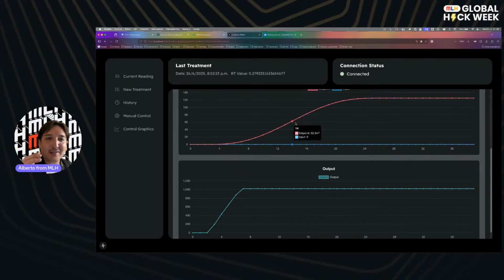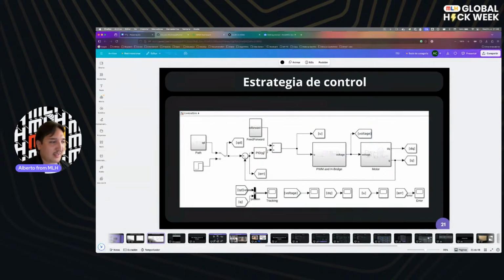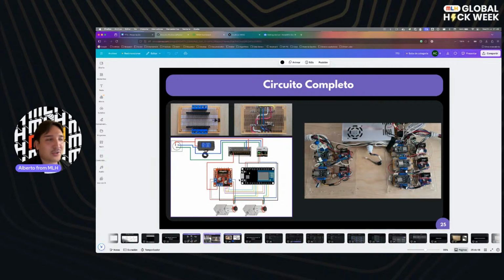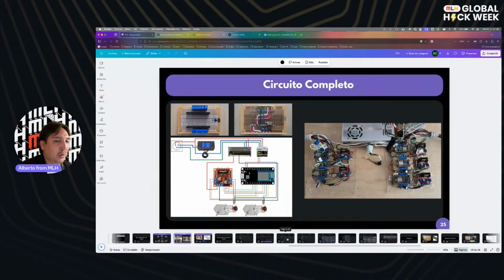So that with the appropriate connections, meaning this, connected to the motors through an H bridge with the two power devices, one of 5 volts and one of 12 for these specific motors, can move the project to do something like this.